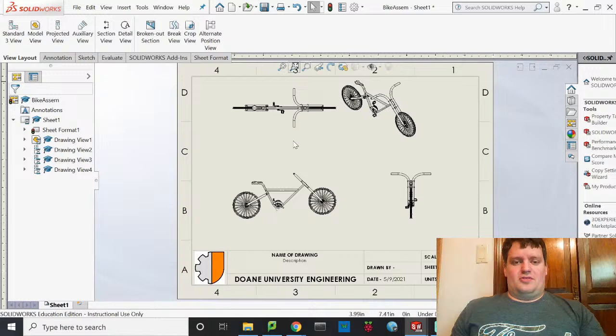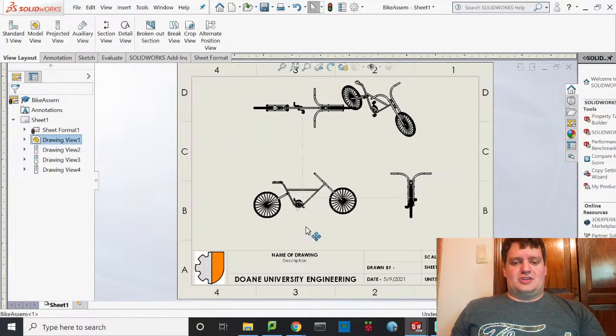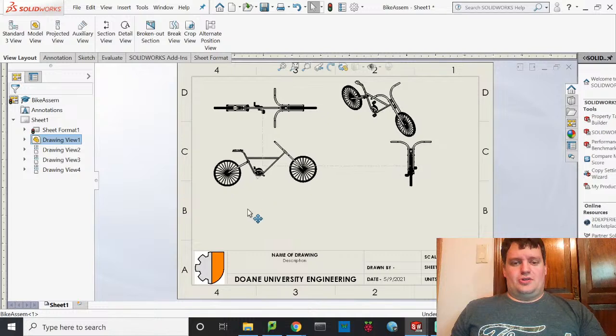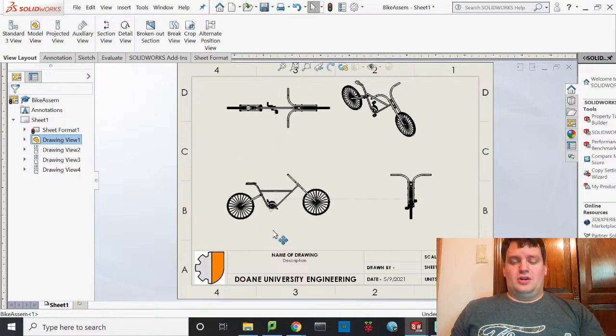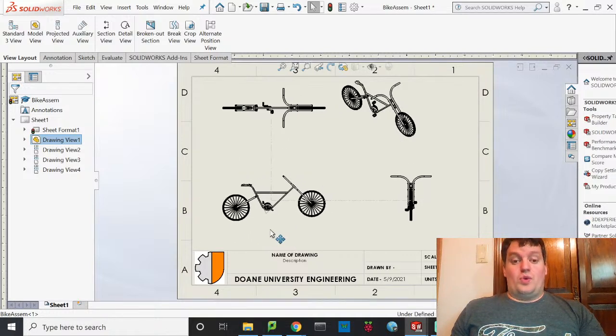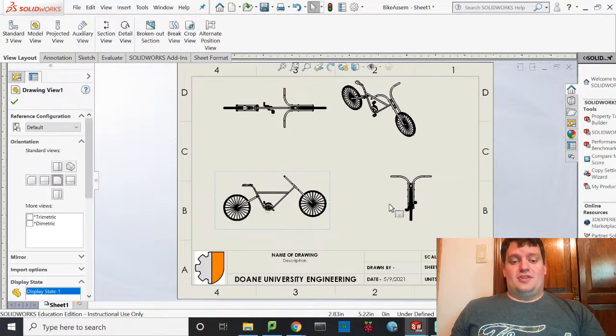It's a single model view with 2 projected views. You can also bring in 3 different model views. The nice thing about this is that these actually do all move with each other. You'll notice if I move the model view, it moves the projected views with them. If I see a pedal here, I can map that pedal location to that one over there, and I can do the same over here. Okay, so that's just some initial points.